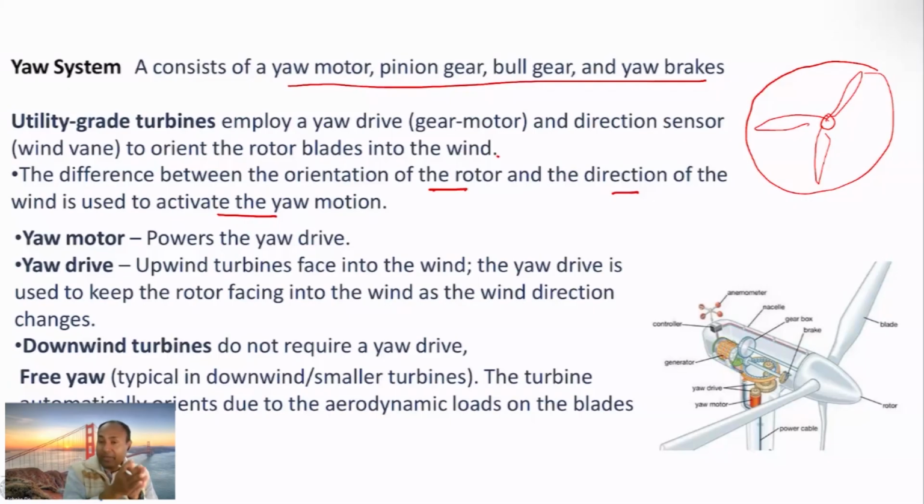But having a yaw drive or yaw mechanism in place, you can achieve that to some extent, though only in a limited way because you cannot have an infinite range. One cannot turn the turbine completely from minus 30 degrees to plus 30 degrees or beyond. Those are just numbers I'm giving, because the yaw angle change would be very small, a few degrees. It cannot be too high because a very large yaw movement is just not going to be possible.